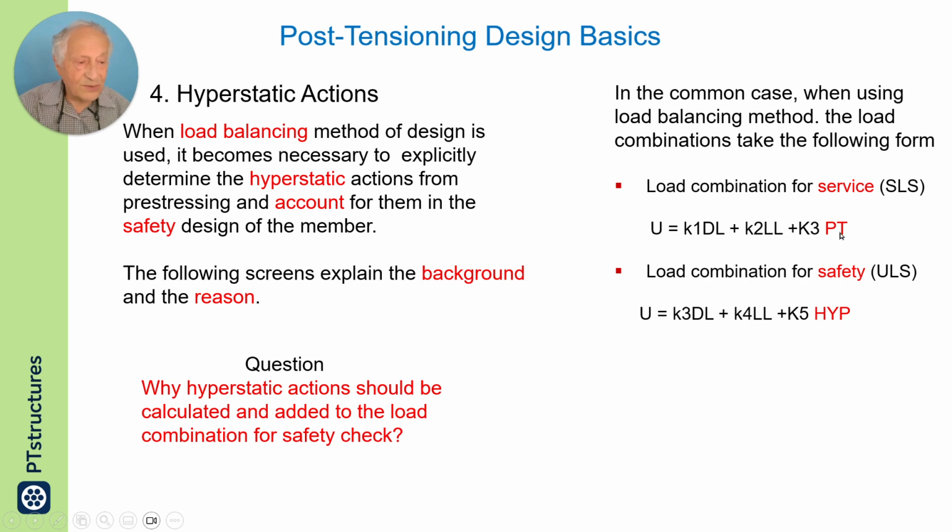But the post-tensioning is not the same. The value you enter for post-tensioning in the service condition is different from the value you enter for post-tensioning in the safety condition. Not so for dead and live. And here is the reason. By the way, before I go to the reason, this feature is because we are using the load balancing method of design.